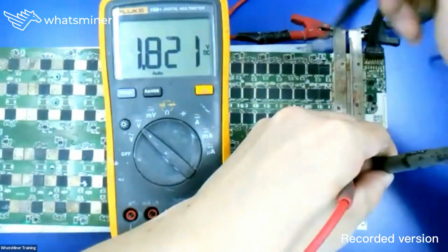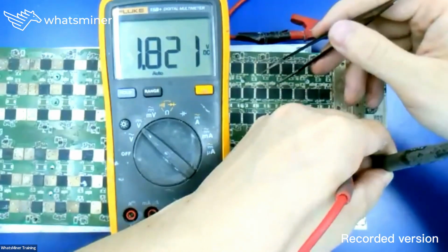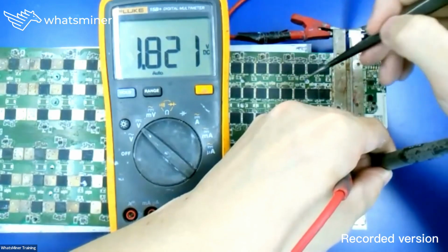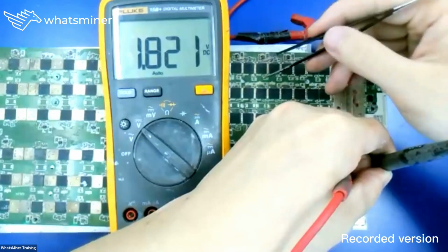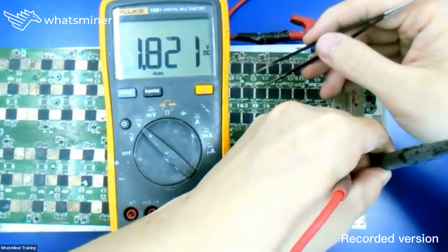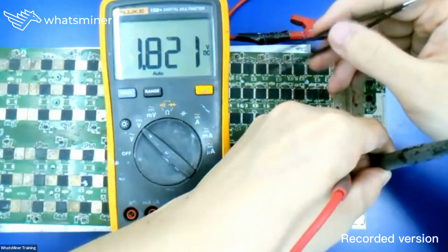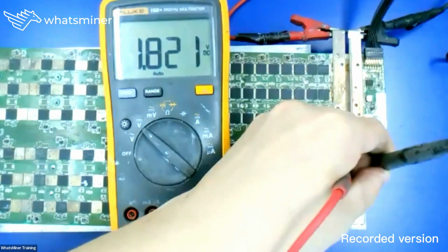The method is the same as for the RxD: jump to any chip and short, but the direction is reversed, until you find that the input of the TXD is normal and the output is abnormal. It can fall to 0 at the input. That chip is the defective one.